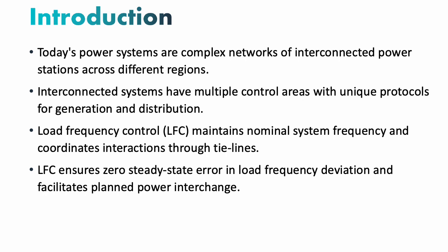These tie-ins come with their own challenges, and one of them is the frequency fluctuation due to load variations. And in order to mitigate this challenge of frequency fluctuation, a power system needs to incorporate an appropriate load frequency controller.